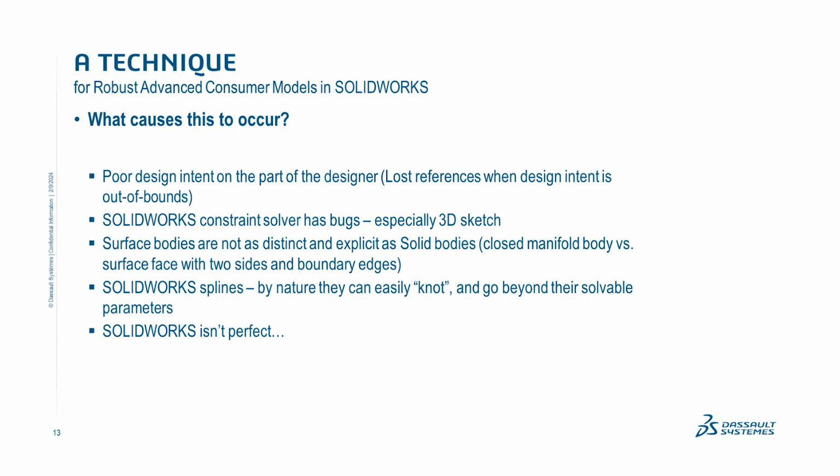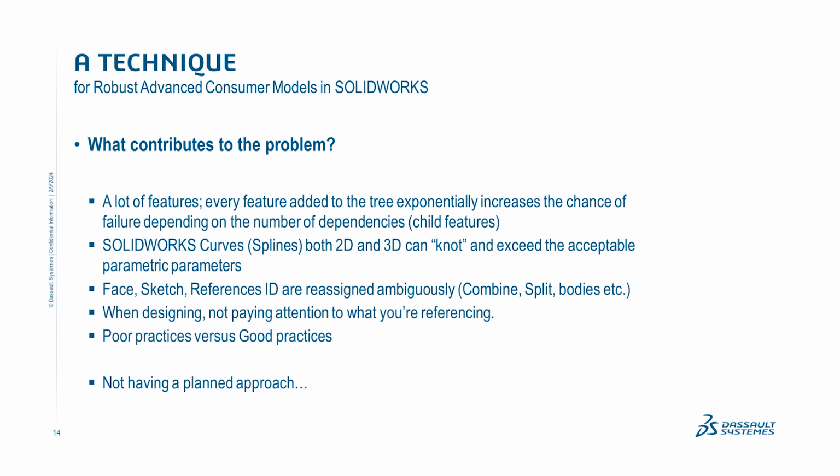So another part of the problem that's, if not obvious to you now, is that when you have SolidWorks parts with many features, you're increasing the chances of failure, because many of those features are dependent on one another. So you're just increasing the chances of a child feature not associating with a parent feature, whatever that constraint is.